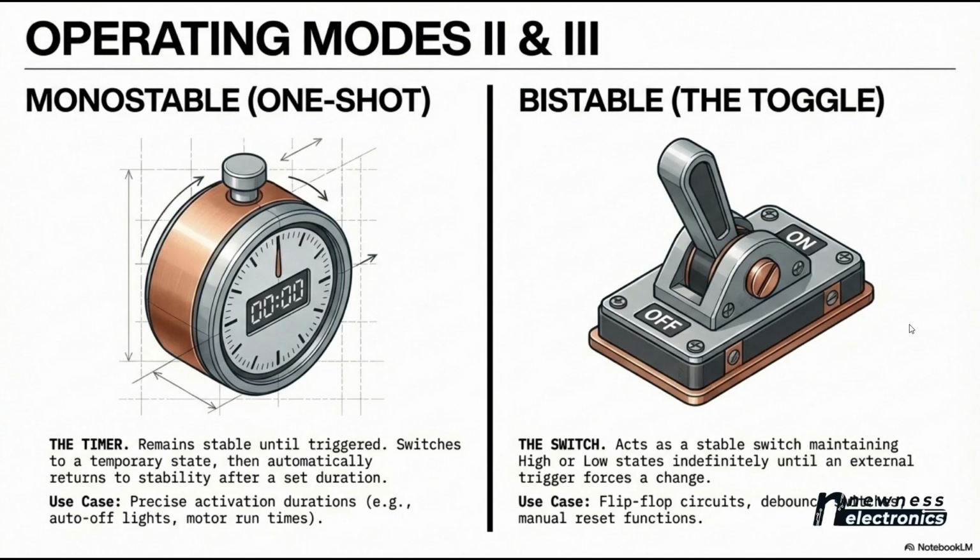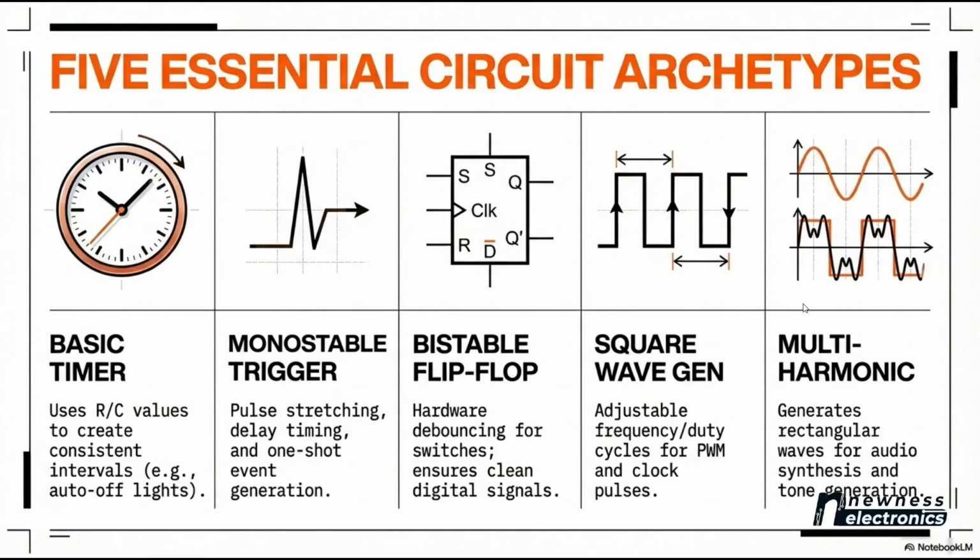Okay, let's continue. And then you have the astable mode. In astable mode, you can make it generate a particular square wave oscillation with adjustable frequency and duty cycle. And if you combine more than one 555 timer together, you can generate different kinds of waveform, different kinds of modulation and tone. For example, if you've heard of this alarm circuit that's saying wow, wow, wow, wow, wow, you can use your 555 timer to generate it. Yes, you can do that.